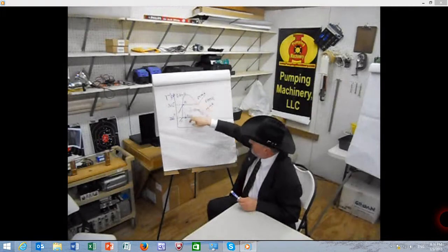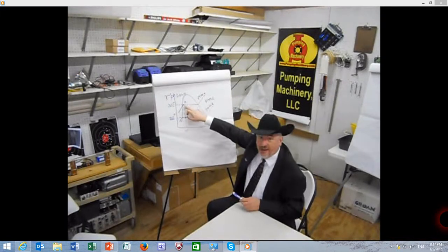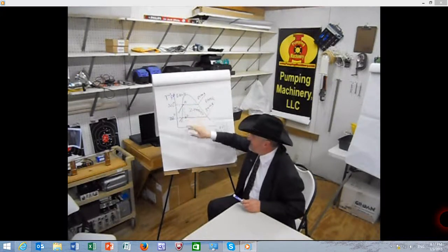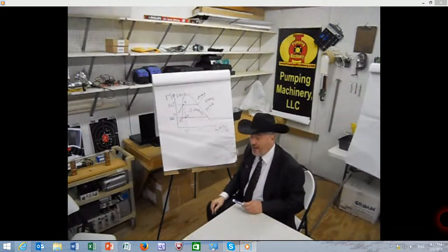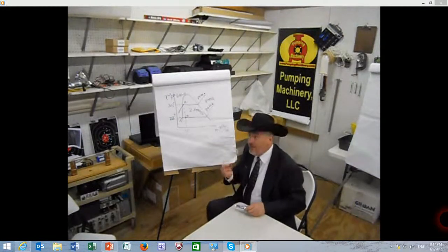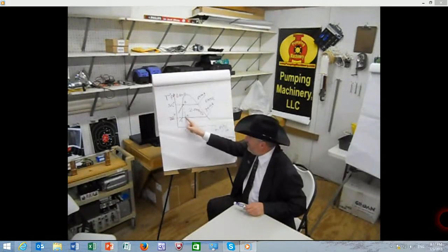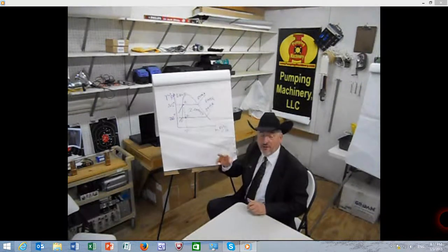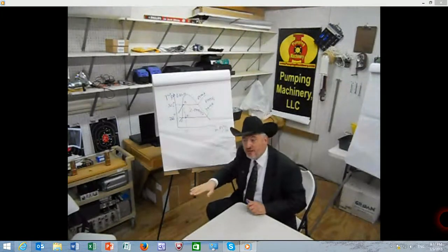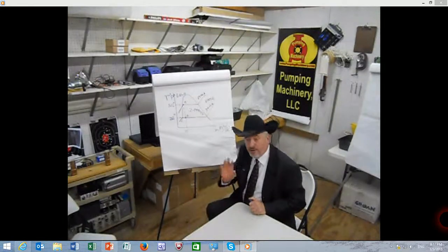So the flashing causes A going to B, and B has a small mass fraction, X. It's called the X fraction in thermodynamics. In mass, it's a small fraction. Most of it is liquid. But in volume, it's a very substantial amount of volume. If that volume gets sucked from the DA toward the suction head up to the pump, problem.